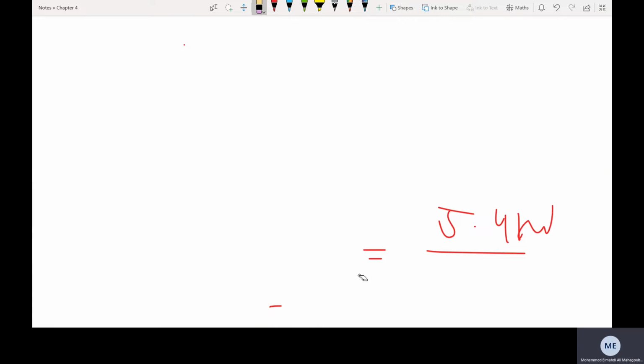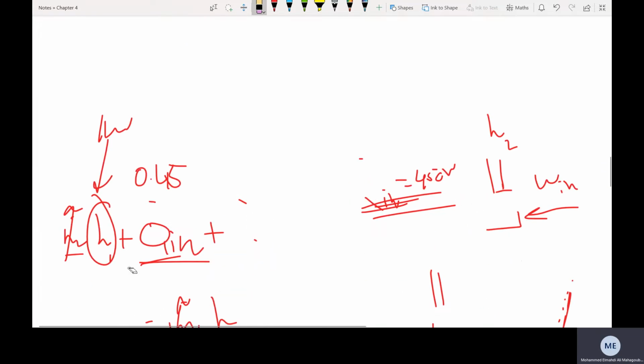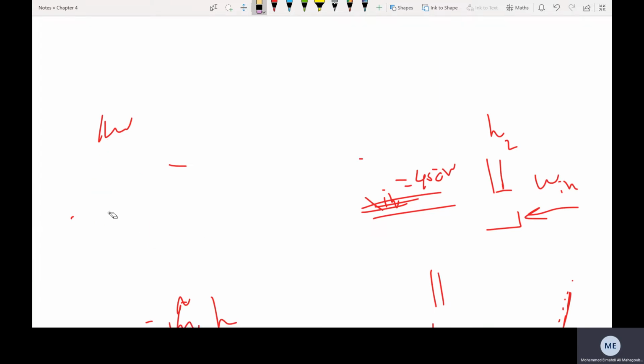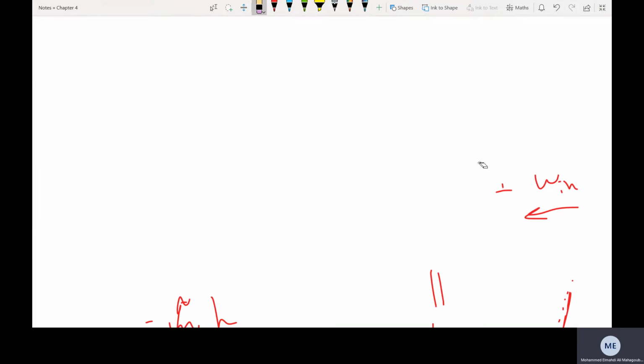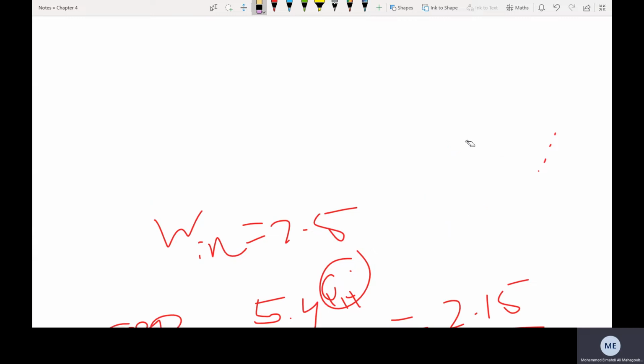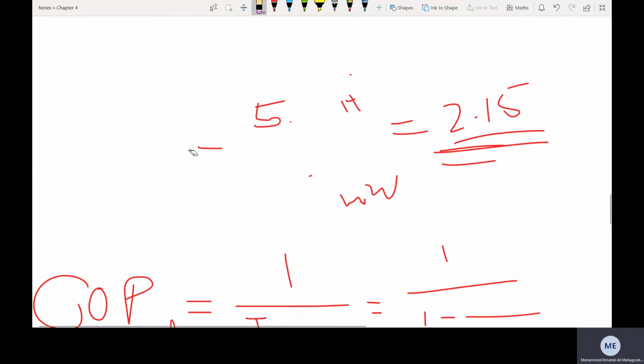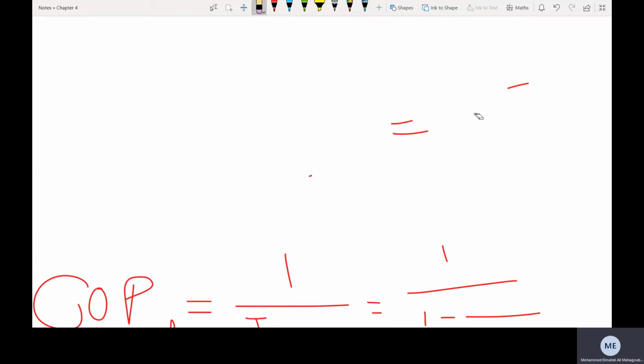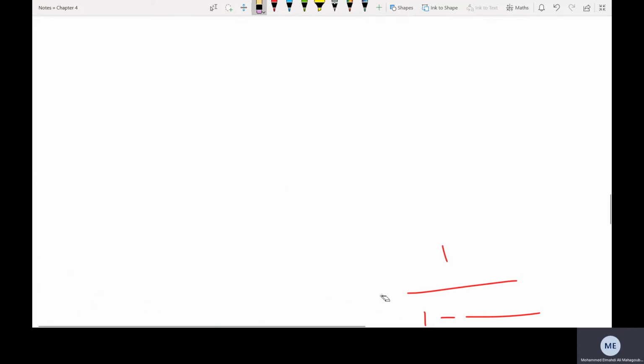While I'm deleting, the cascaded cycle is just two vapor compression cycles on top of each other. That's basically it, nothing more, nothing less. You have now a third pressure in the cycle, which is called the intermediate pressure. Sometimes this intermediate pressure can be the same for the upper cycle and for the lower cycle, and sometimes it's not the same.